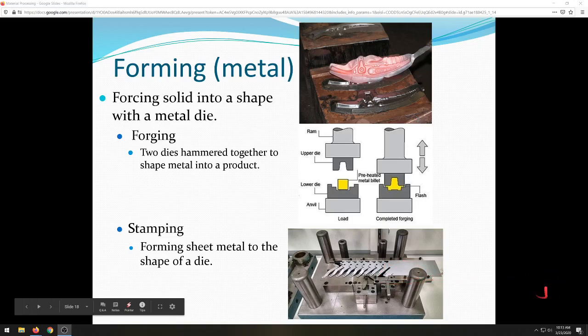Basically, back here you'd have a big spool of material feeding out this sheet metal, and the die is going up and down really rapidly. It's probably auto-fed, would be my guess. And it just goes doop, doop, doop, and every time the metal stamps, ka-chunk, a part gets spit out, but then new material gets fed in. It looks like step one is punching this hole, step two is removing this little bit of material, and step three up here is one of these two little holes in the slot. Eventually we get into bending and shaping, and then eventually the part is cut off.